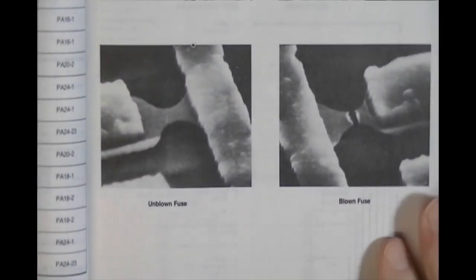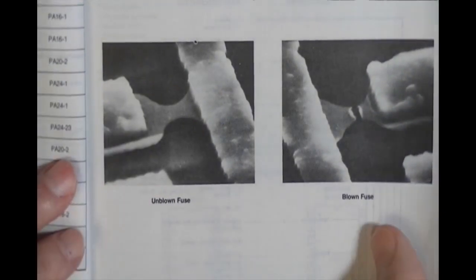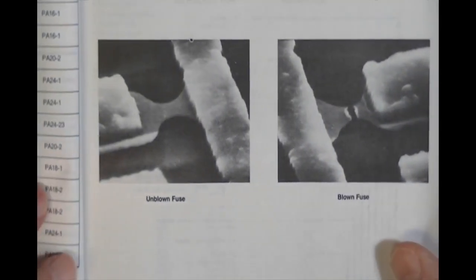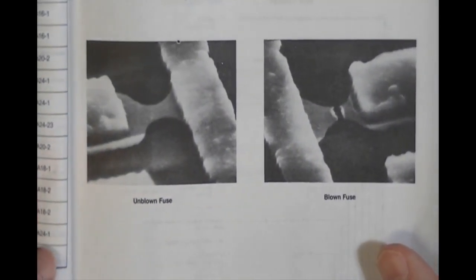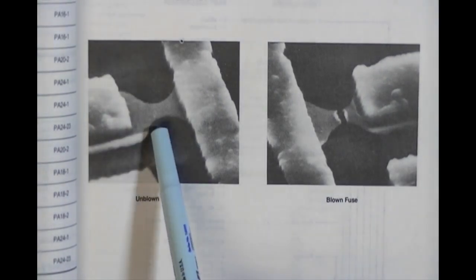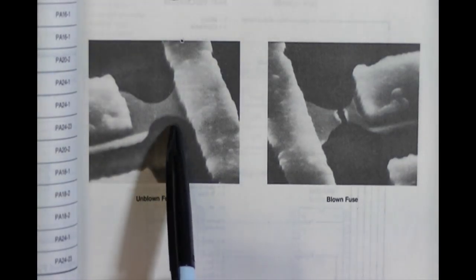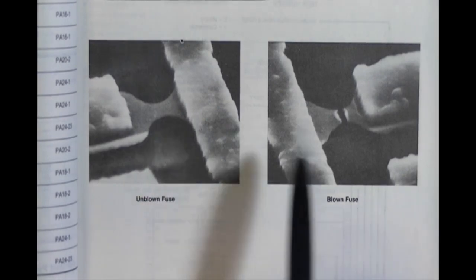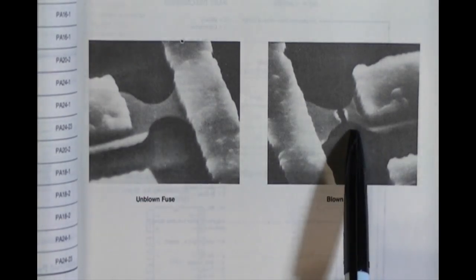What you can see is that we are blowing little fuses in the bipolar prom. When a bipolar prom fuse is intact, that's this guy here, the bipolar prom will read this bit as a 0. Once you blow the fuse, the bit will be read as a 1.